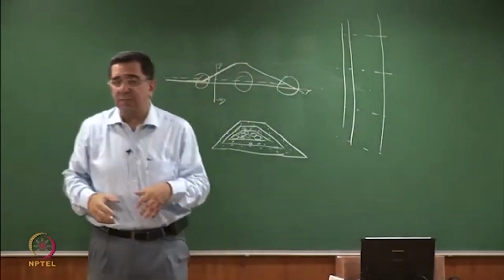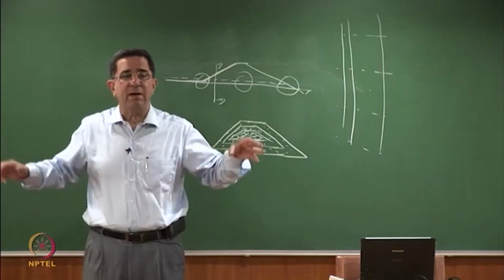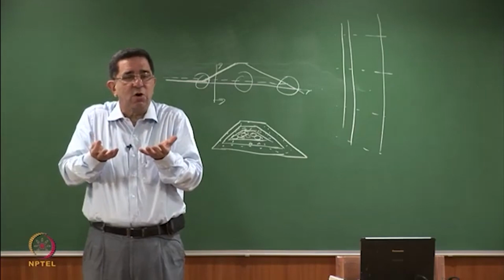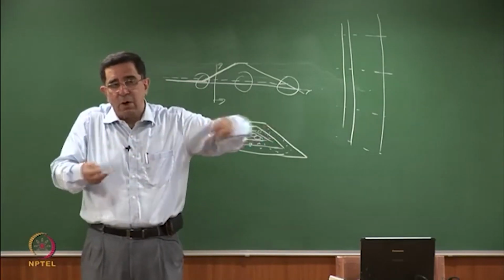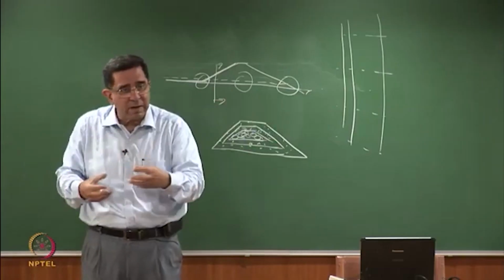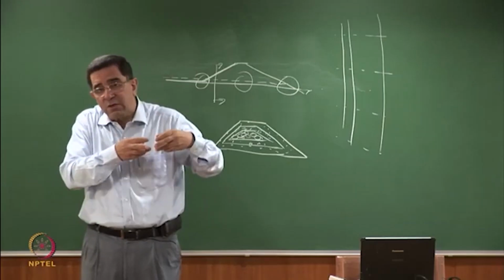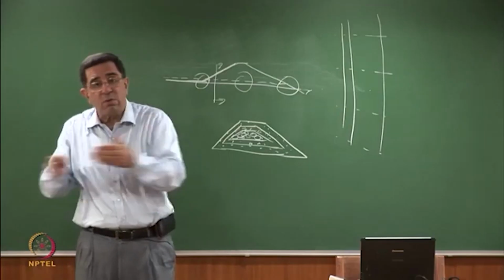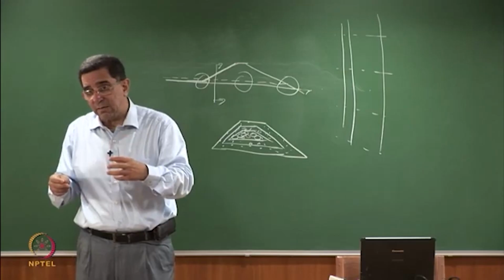All that we are saying is, if you are putting a liner, it should be a bottom drained liner. That means any liquid which is resting on top either goes to the well, in which the bottommost ports still allow water to come through, because by putting a gravel pack around them, and you may still allow passage of the water to drain out through the embankment as well by properly designing it.